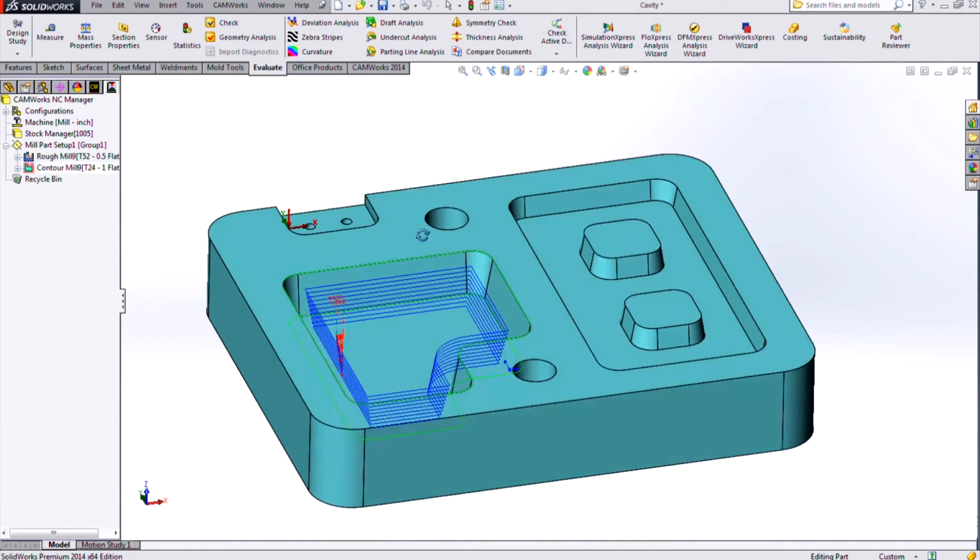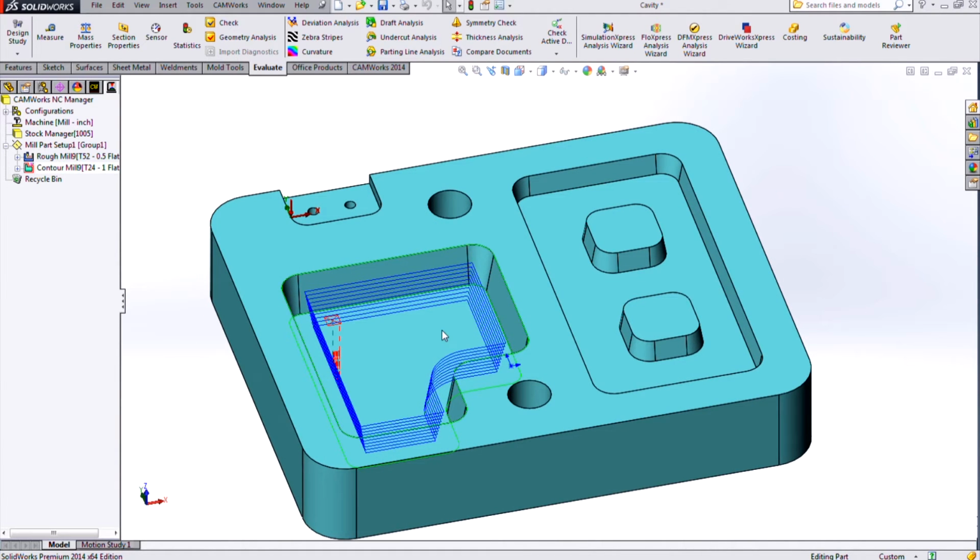But next we want to take a look at this: if you're machining these pockets frequently, you'll probably be using a tapered end mill. In that situation, we want to define our pocket so that we don't taper it down like this. We don't want to double compensate for the fact that we have a tapered pocket. So we'll look at the procedure for defining a pocket when we want to use a tapered end mill.